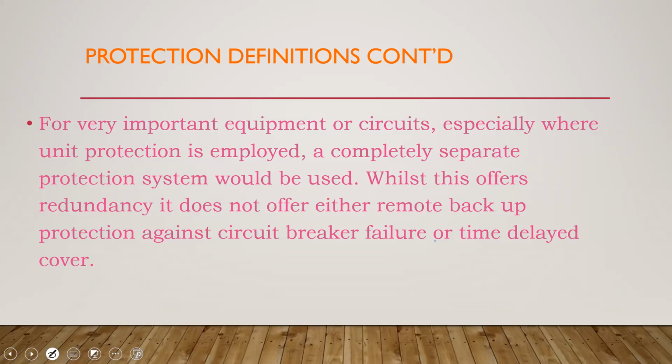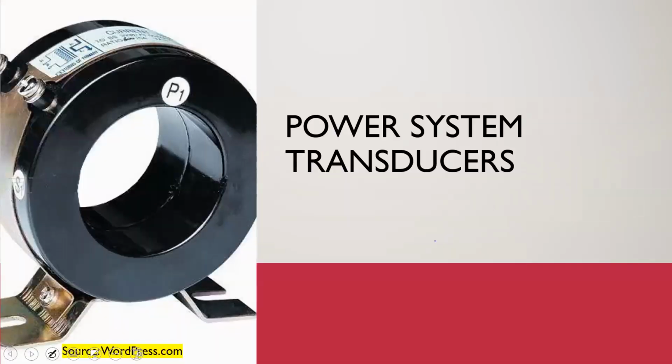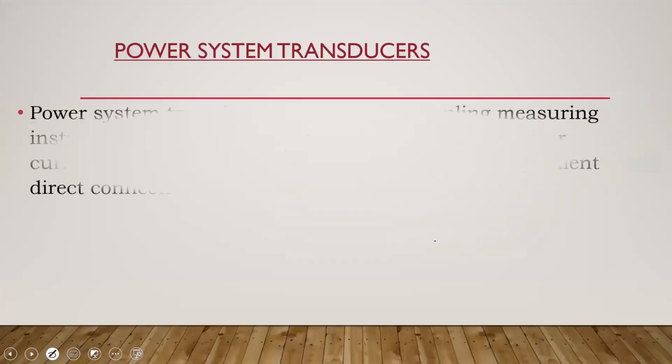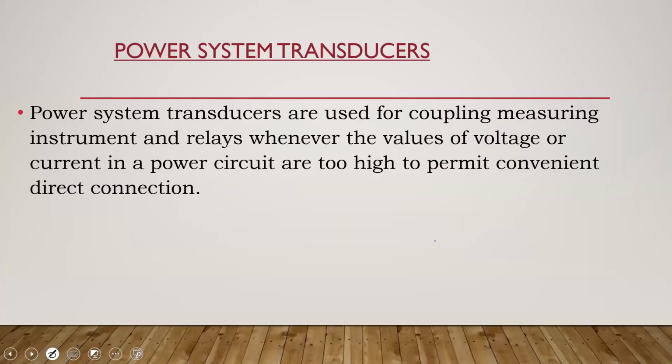Okay, so the next thing we want to quickly look at this afternoon, we have 10 minutes, we want to talk about power system transducers. And the transducer, we all know what a transducer is. In power systems, we are talking here about your CTs and your VTs, your current transformers and your voltage transformers. So your transducers are used for coupling measuring instruments and relays whenever the values of voltage or current are too high.